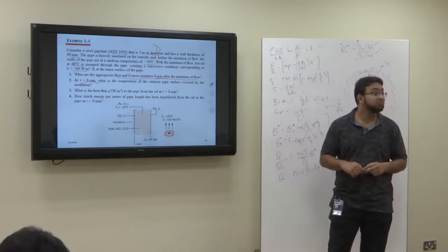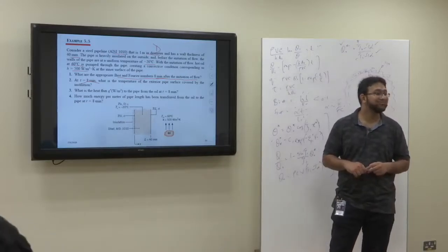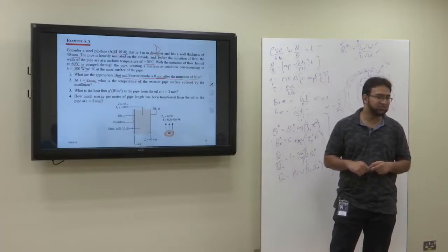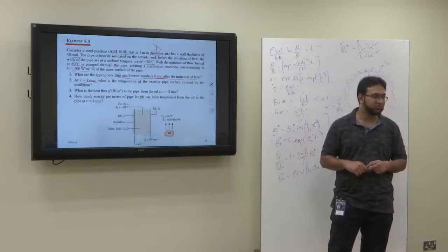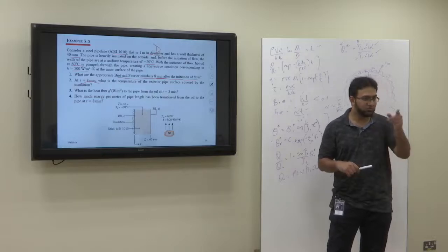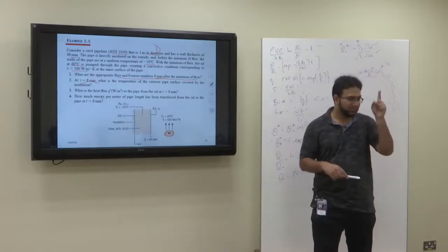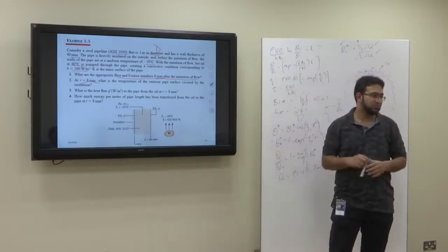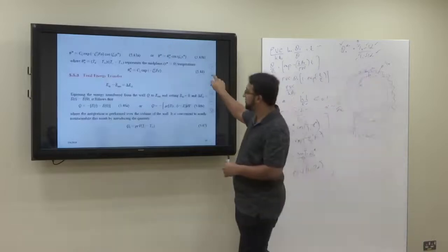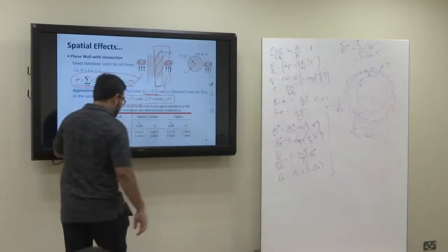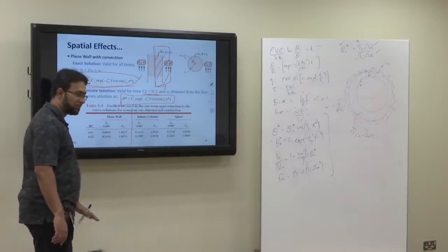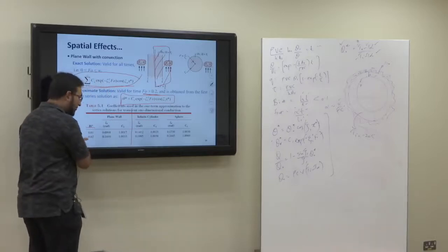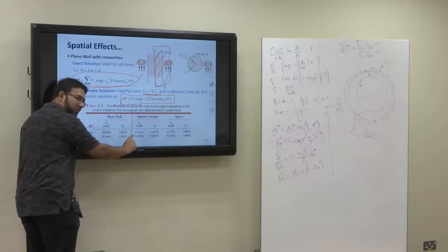In material, quantify the material. That was tricky to find. That's using the tables: eta and constant C1. Use it from the tables 5.1. Get the Biot number, and from the Biot number, find out the eta and constant. So you have this table, which is just the start of the one-page table. Whatever Biot number you have, corresponding to that, find out eta and C1 for the plane wall.